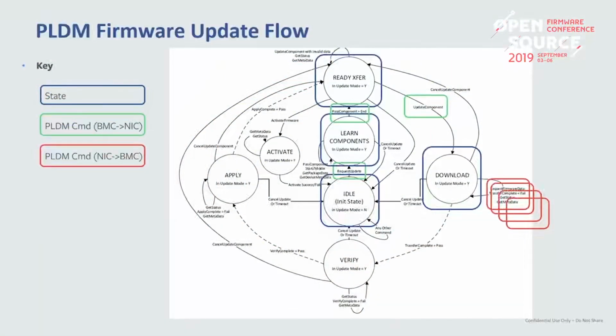So right here, the device takes over, and the device tries to dictate when it's ready to receive the next data transfer. BMC sits idle. The device sends a command to BMC requesting a chunk transfer and specifies both the buffer size and also the offset. There is actually no requirement for the device to do this sequentially. From what I see, it's useful on the BMC side to keep track of all the offsets that the device has requested. Because we have seen cases where, out of a 10 megabyte transfer, the device actually misses a few chunks.